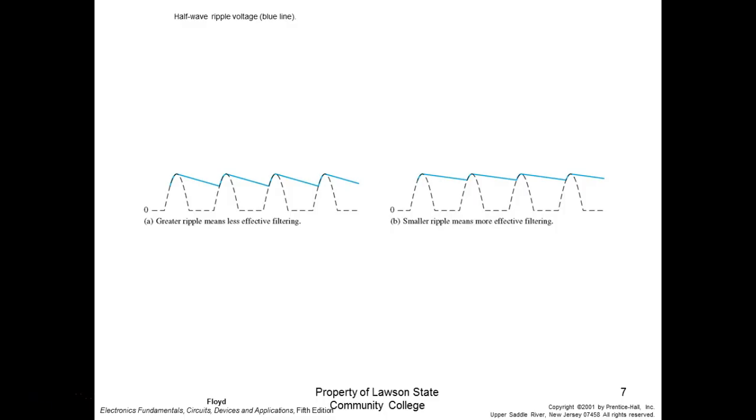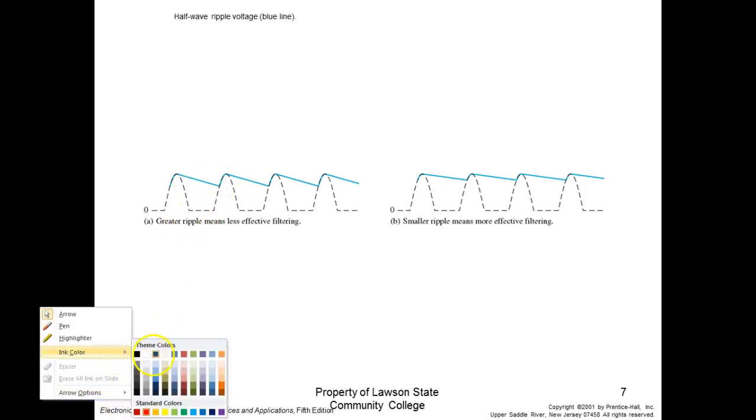T is equal to R times C, right? So, half wave, if it's 60 cycles, then that's probably what we use. And you can see the higher the frequency, the shorter time it has to collapse, right? You understand? So the shorter time the thing has to run the load. So it means I could use smaller capacitors if the frequency was greater than 60 hertz, right?